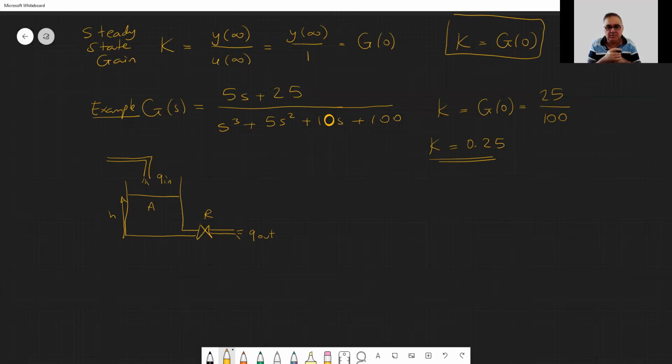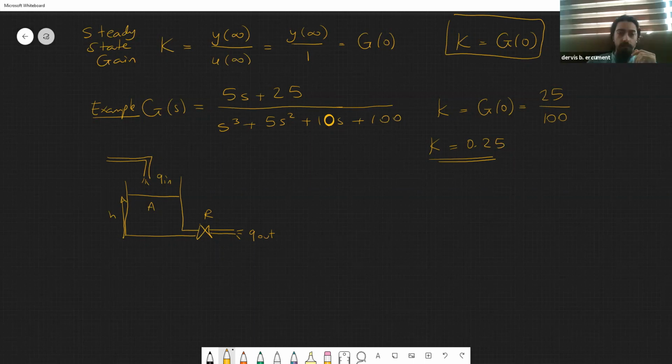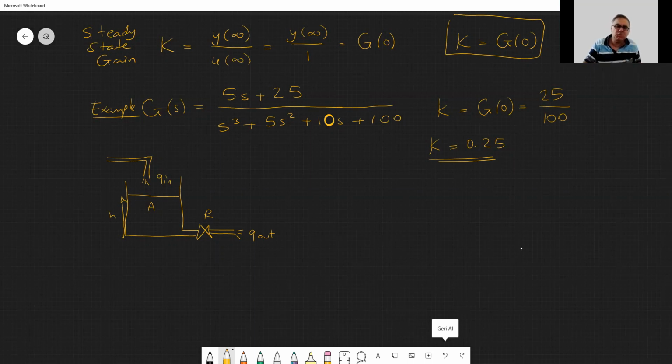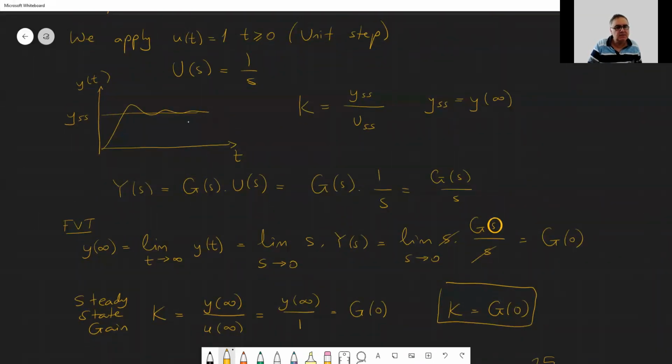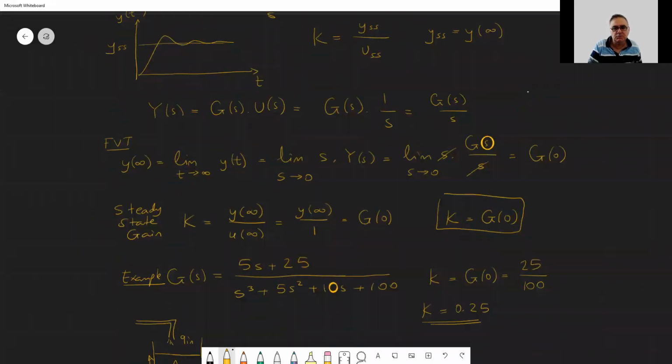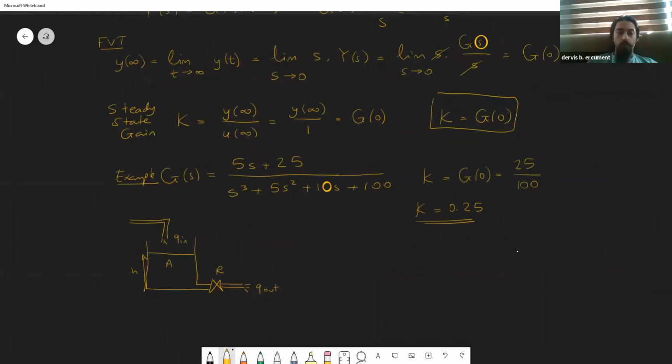It is a gain at which the time derivatives are 0. So you have to have some kind of an input, which is something like a step. Yes, that's kind of true. Because if the input wasn't a step input, the s's wouldn't cancel, right? Because we multiplied the transfer function with s. Yeah. Well, we chose the step input because we know that with a stable system, with a step input, the system response will settle down. That's why I chose a step input. Okay, hocam. Thank you.